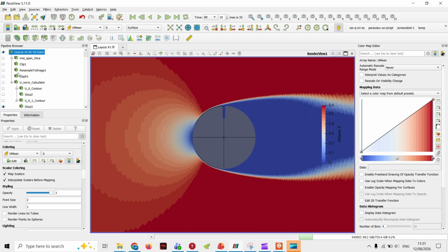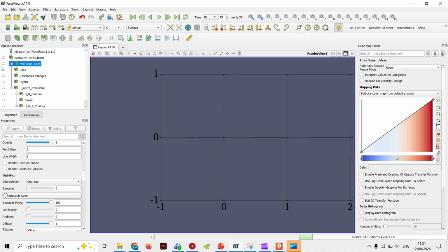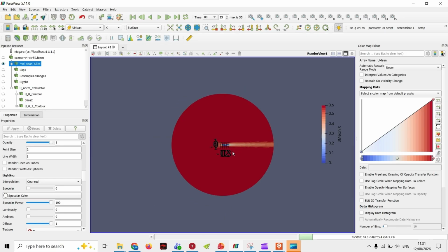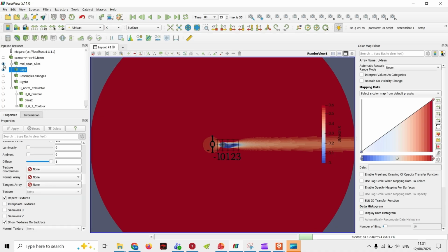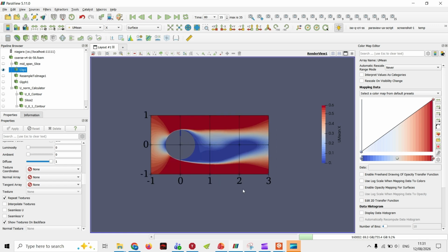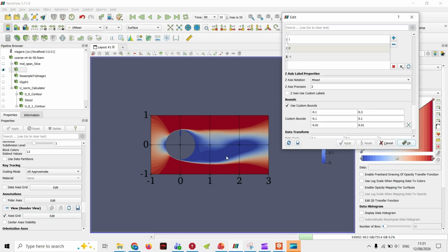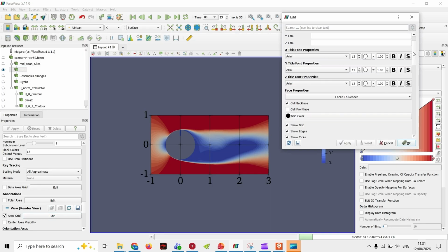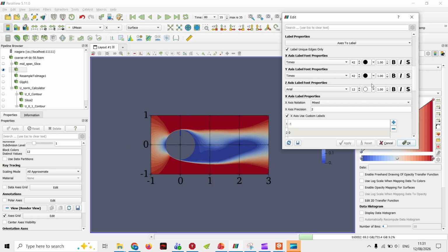Now, let's have a look at the pipeline. So first of all, I took a slice at the midspan, and then I used the clip feature to clip it just so that I'm only showing a box around it. Now, the axis grid, usually I fix this towards the end, but basically I changed the color, I removed the title axis. The reason is that I don't think there's a way to set the distances yet, at least not in the GUI version.